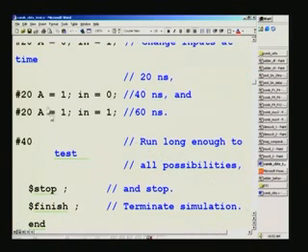One more thing we have mentioned in this: the test bench is applying inputs at different points of time. We have seen that the test bench gets the very same waveform as you have in the design. Only then will you get a feel that what you have really connected appears on the top level. The test bench is always the top level. At least once you should verify that it is actually reflecting the design wherever you have connected. Once you have done it, there is no need to do it every time. I mentioned that just to give you a feel for it.